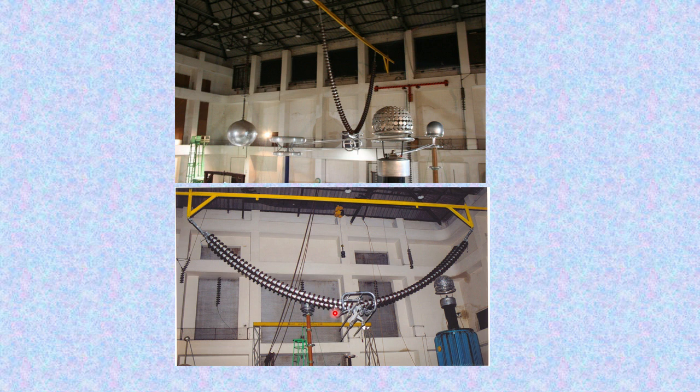So, what happens in case failures are observed, and how much will the stress be increased in the adjacent insulators? That we will be looking at also after this, in the tests which are being shown here. We will see how the performance of the string behaves in case there are faulty insulators in the string. Faulty could be anywhere in the string. So, how the performance or the grading or the potential distribution gets modified.